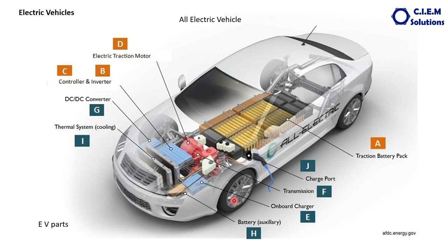The next one is the on-board charger. A charger is provided inside the vehicle itself so that we can plug into the domestic supply and this battery pack can be charged. But the only issue is it takes a long time to charge these batteries from this onboard charger, because the amount of voltage or power supplied to this charger is a domestic power supply. It takes almost 13 to 15 hours.